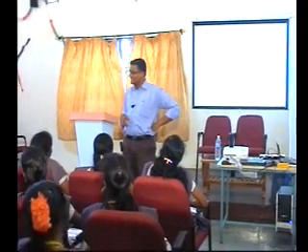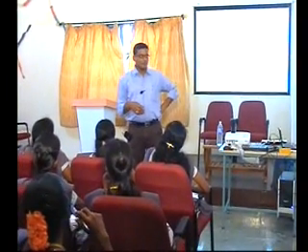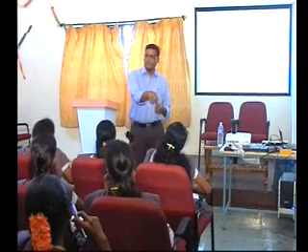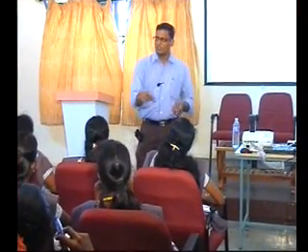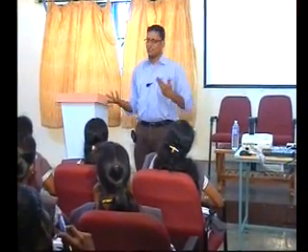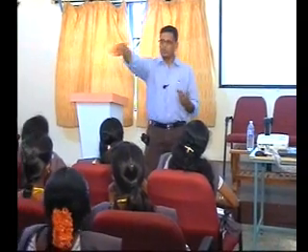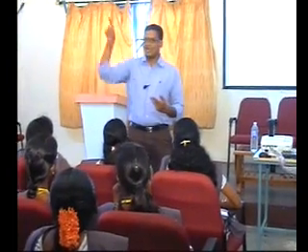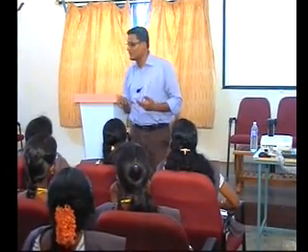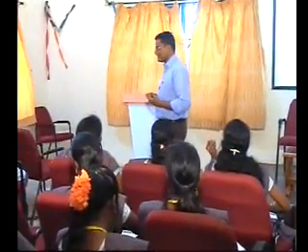Correct or not? So that means I have done this thing immediately after asking her 0. If I ask her now what she said, easily she says 0 only, sir. But I made it for 2 rows, then only I asked the girl. This fault is called as data retention fault. What is this fault? Data retention fault.